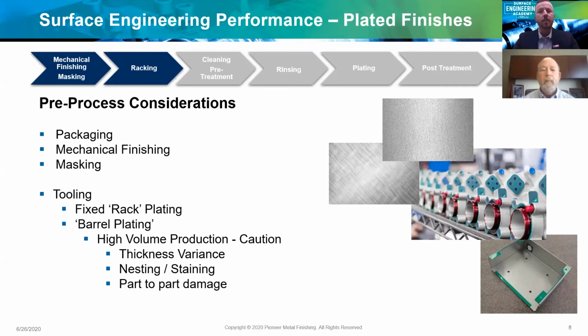So wanting to keep those in mind, obviously with an electrolytic plating process, you have more of a deposition at an uneven rate, and so your surface texture will become more muted versus electroless. So keep that in mind as well. But that's really how you would control luster or shine versus, say, a matte finish, is mainly in the mechanical pre-treatment of the substrate.